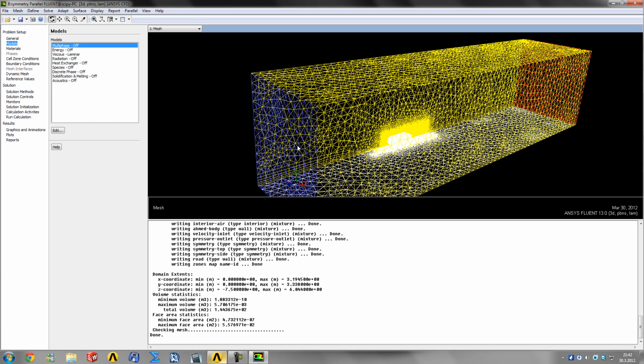If you were trying to investigate the effects of, let's say, exhaust gases or very hot exhaust gases, you would need to turn on the energy equation, which just means that it would solve for temperature and heat next to all the other equations that it will be solving. But we are not going to do that, and obviously the energy equation is needed to capture the viscous heating and those types of effects, which we are also going to ignore for now.